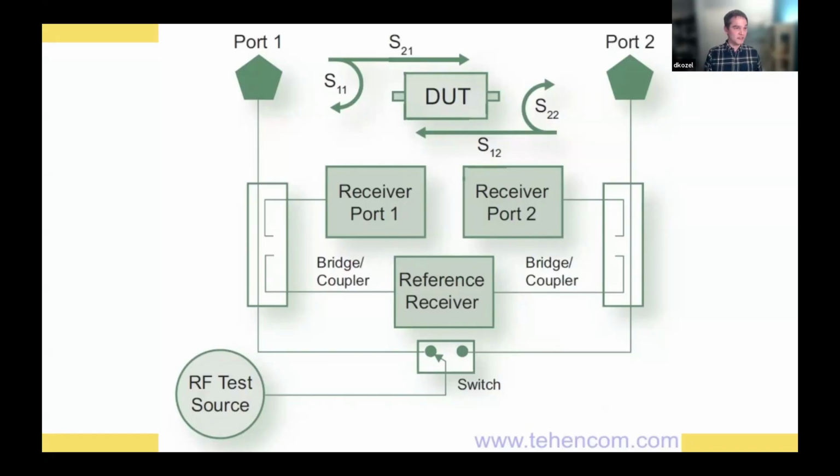And so something like the NanoVNA, and most modern, or most historical VNAs, I should say, as well as many that you would buy today, will just put out one frequency at a time. They'll put out a test tone, switch it to port 1 or port 2. With the NanoVNA, an interesting point is that it can only put power out on port 1. And the first thing it goes through is a coupler, and it samples off a small amount of that transmitted signal. And it considers that its reference. Then as the wave goes outwards, it hits port 1.